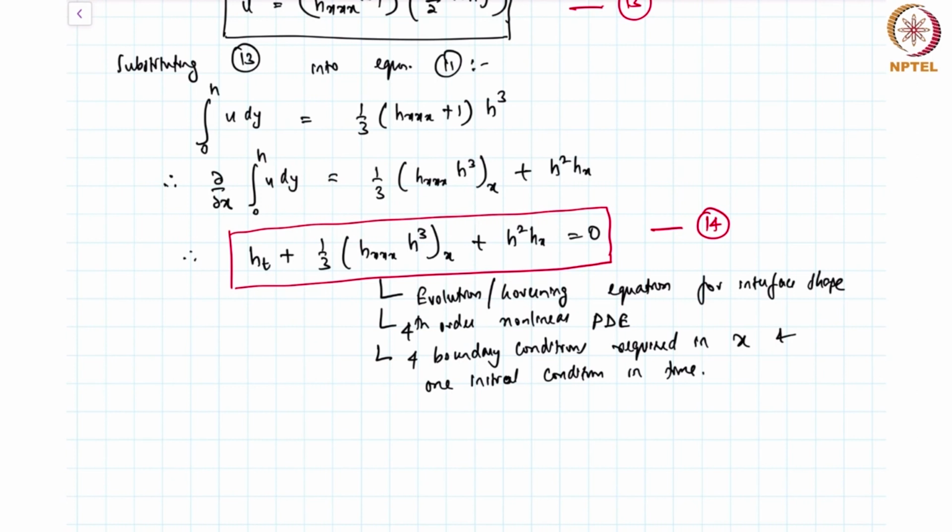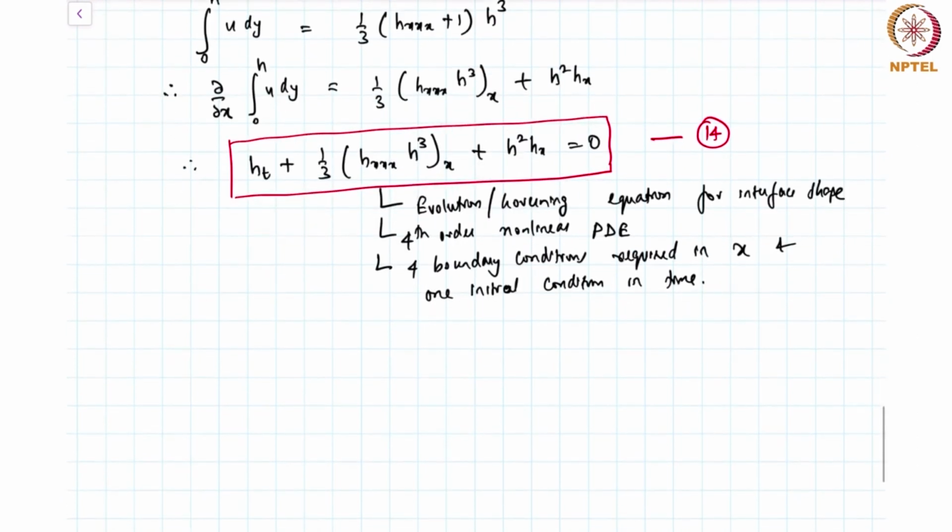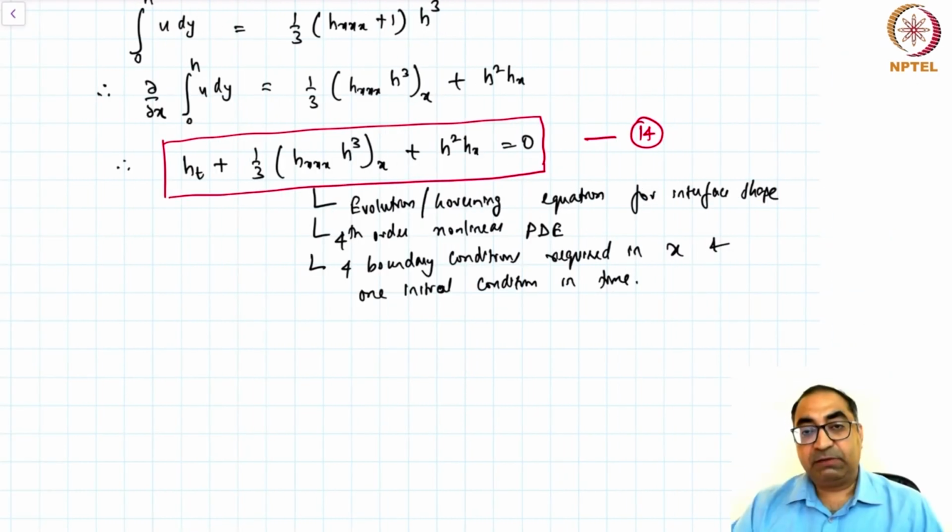Okay. So let's take up this problem in the next lecture. The first part of the goal is satisfied. Now the boundary conditions would involve a boundary condition that the interface meets the solid at the contact line where the height goes to 0. We have to provide the contact angle condition which relates the slope of the interface to the contact angle locally. And then we have far field conditions where we have a flat thin film.